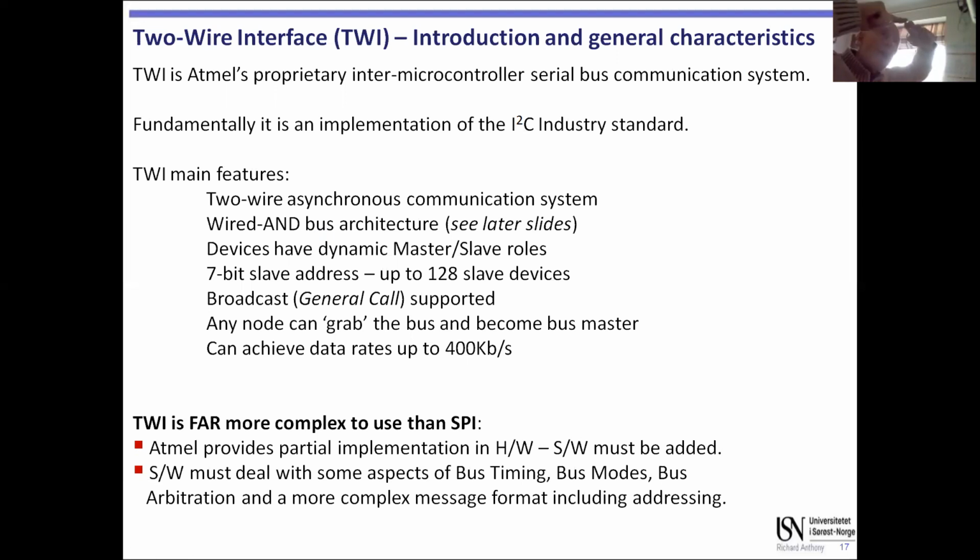And so if someone is doing nothing and someone else is transmitting, then the one that's transmitting will win the argument, if you like. The 0 is pulled low by a transistor in the device, and the 1 is just a pull-up resistor that will just pull it there by default. When you see a diagram, it will become clearer.